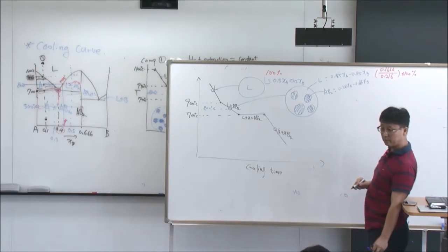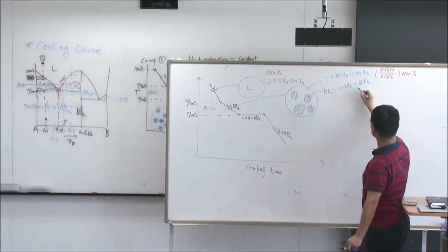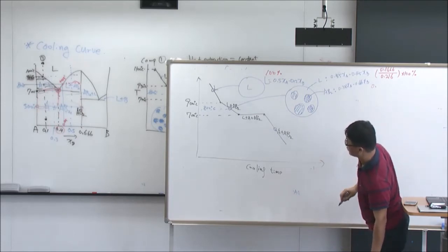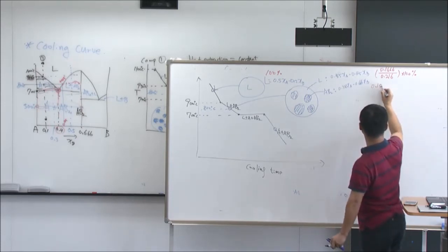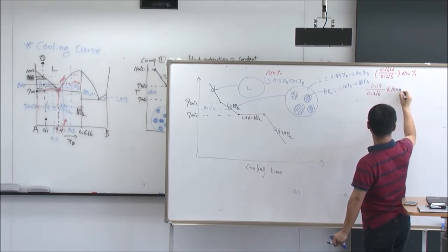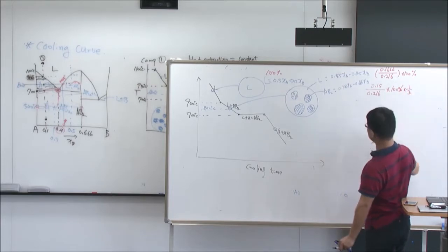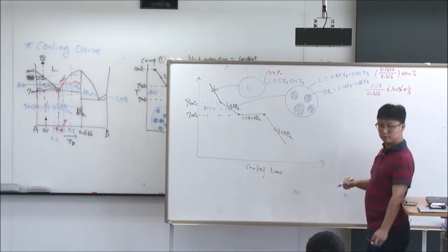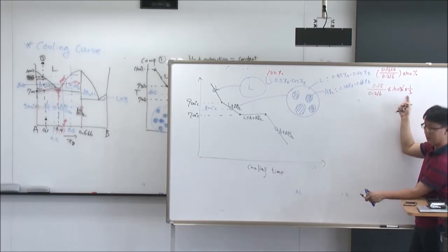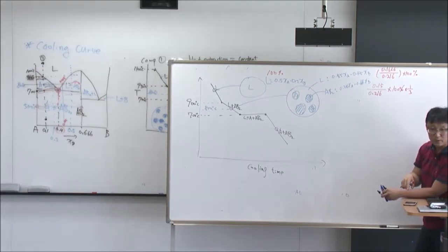That's the amount of liquid phase. The amount of solid here, AB2, is 0. Now then 0.5, so 0.15 over 0.216 times 100%, and then divided by 1/3 because of AB2. So the percent of AB2 is divided by 1/3. Or times 1/3, sorry, not divided by 1/3. Divided by 3. Yeah.